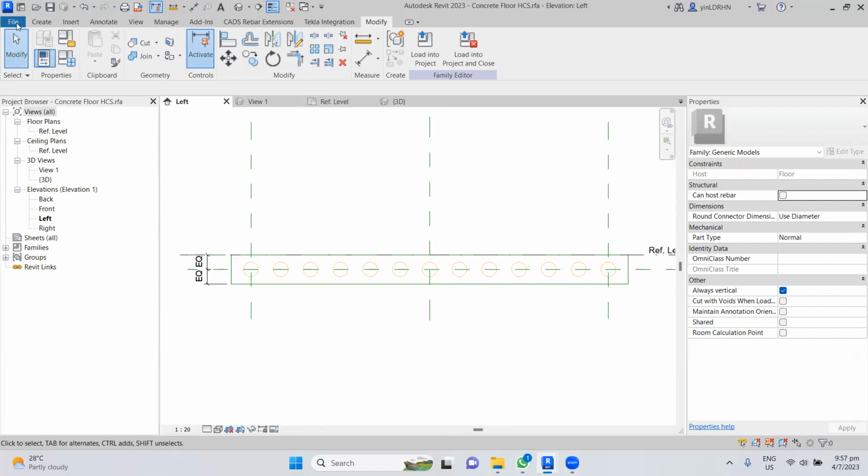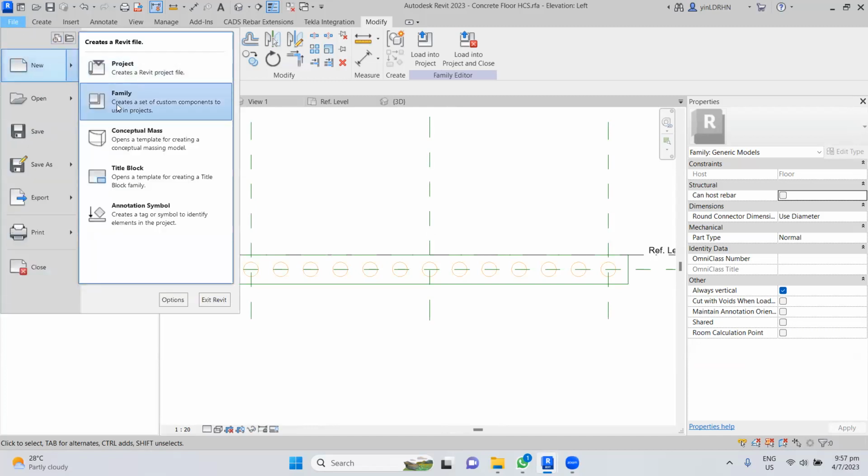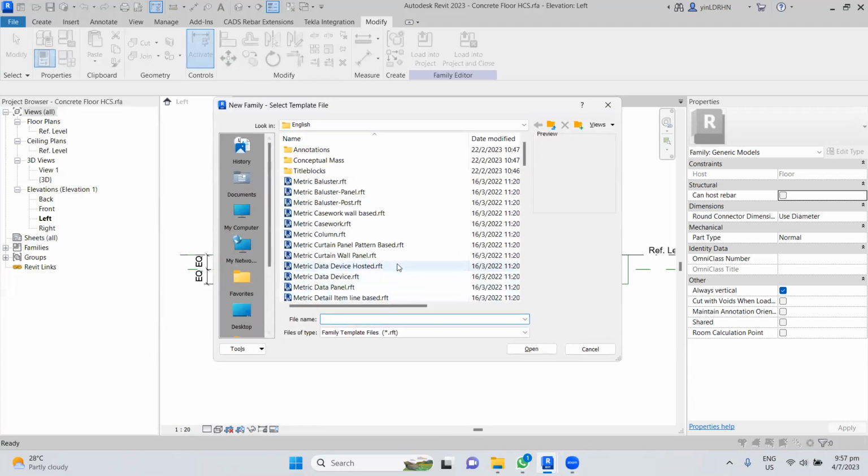Okay, if not, the family is not only used for geometry creation. It can be used for annotations. You remember last time when we did the annotation, I explained how to edit the family, right? Actually, you can create your own family for your own purpose. They already have the standard families, so you can modify from there. Basically, you have to choose a correct family type, then you can modify it or totally create new things.